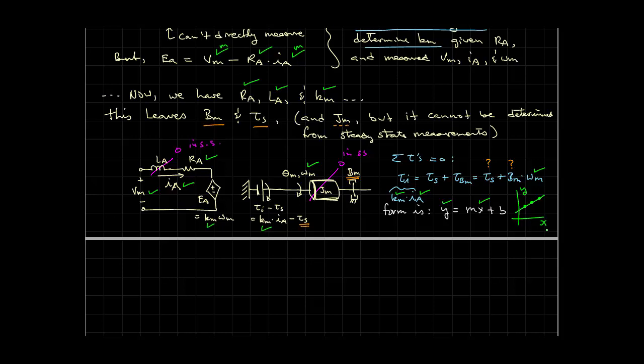If the current changes very little over that range of voltage, then if you're going to set up a test where you program a fixed current, Ia, that's going to be pushed into your motor, your motor speed and operating point will be very sensitive to the current that you apply, because after all, over this span of input voltages and RPMs of the motor, the current changes very little.